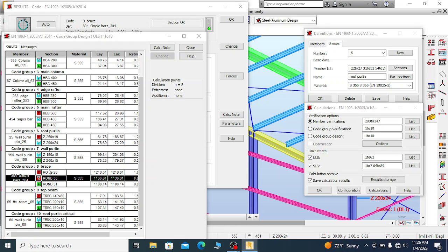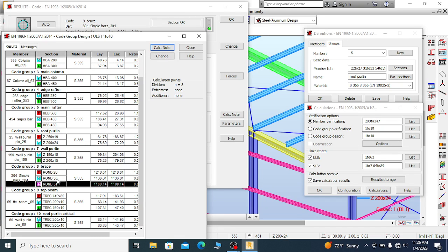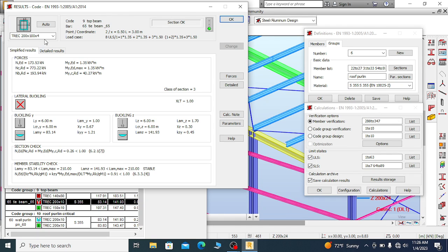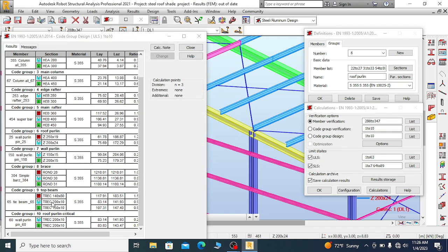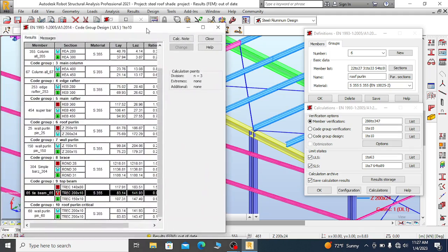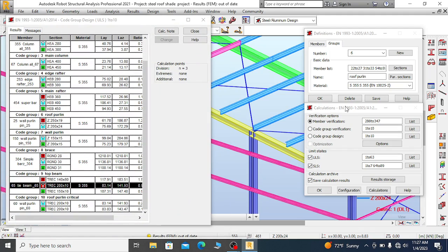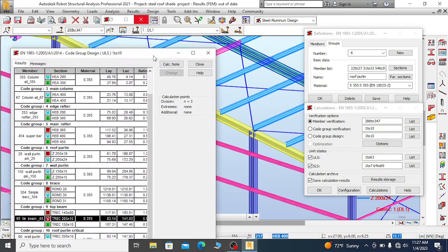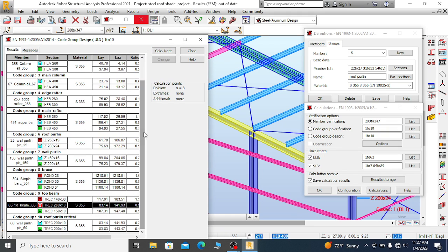So we can use a 30 millimeter round bar for brace elements, and we can also use the rectangular hollow section with 200 by 10, and the cross section, you can see here, is 200 by 10 by 4 as the top tab. Okay, here.